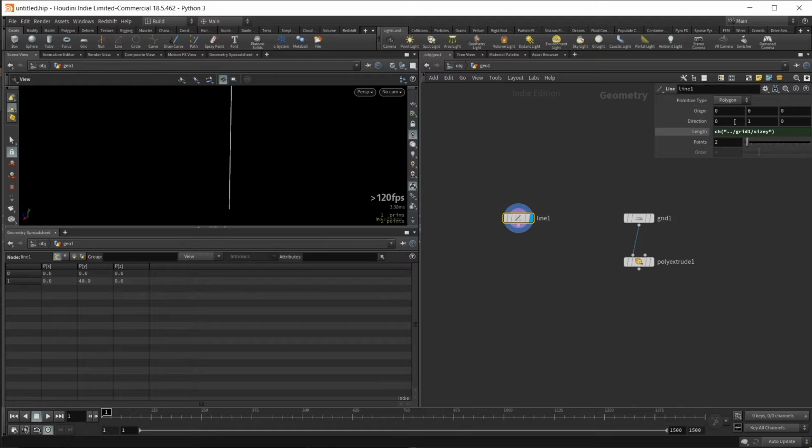So I'm going to change the direction to be 1 on the X and 0 on the Y, and see if that lines up. It looks like this direction should actually be on the Z. So I'll type it in like so. Now if I have a look here, I think they're kind of going in opposite directions. So I'll set my direction to be -1.